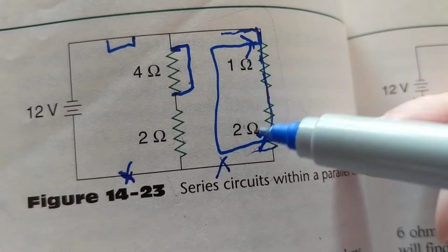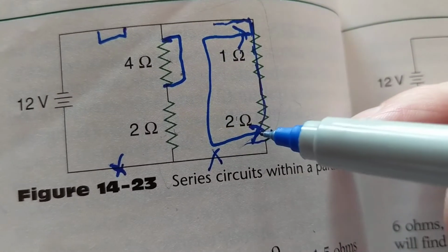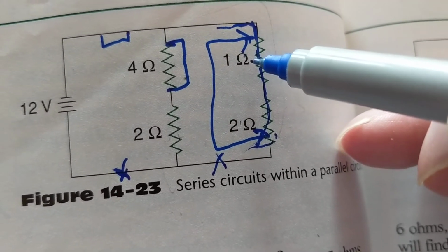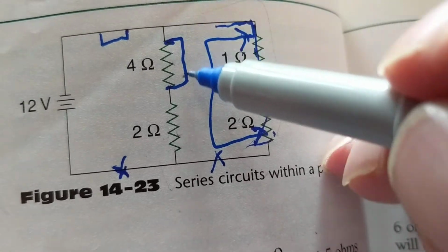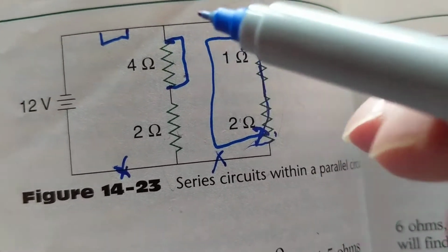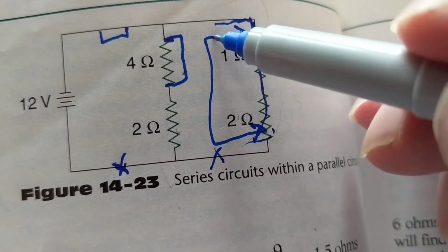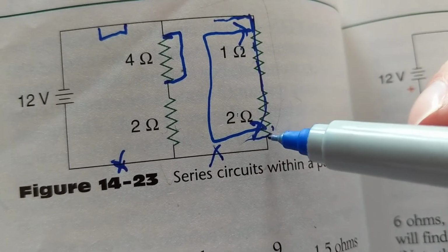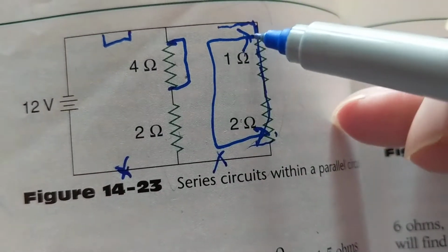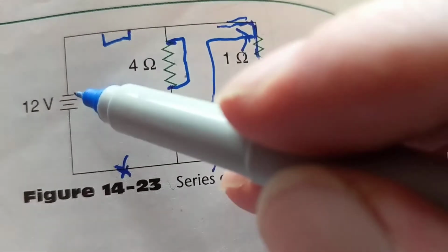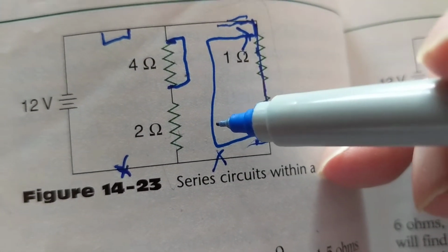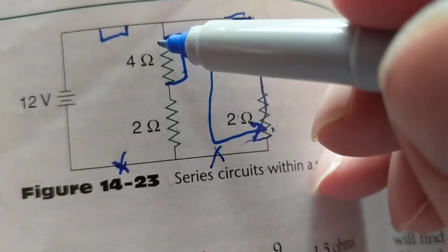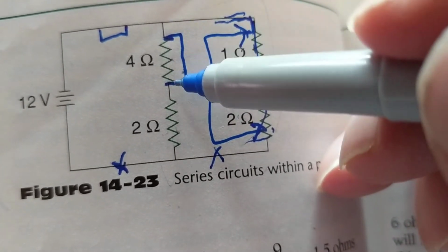This is 0 ohms across. I just took a jumper wire and I shorted out this. Right? This is not a complete short, a dead short. This is just shorting out the resistor. There's a difference. This is a complete dead short. Where is this connected to? Positive. Where is this connected to now? Negative. We just shorted out the battery. Bad. Right? This one shorts out just the individual resistor.